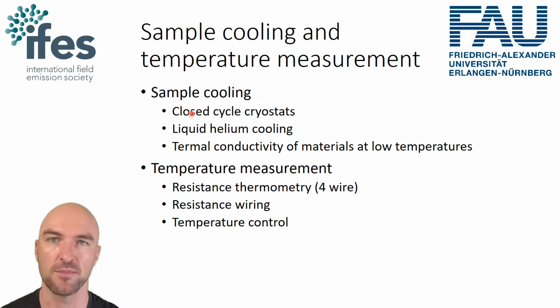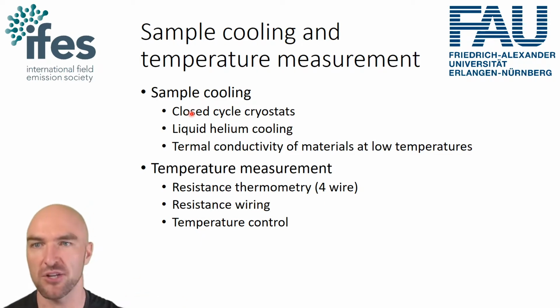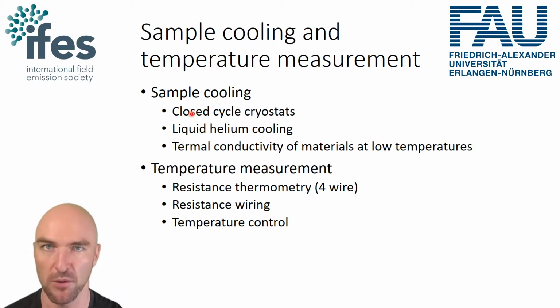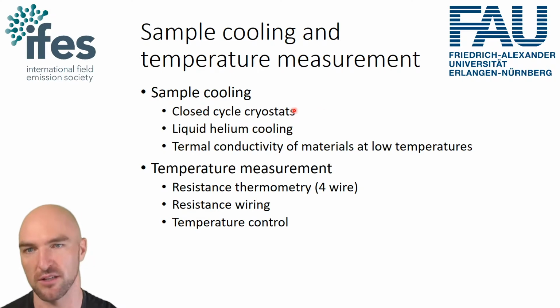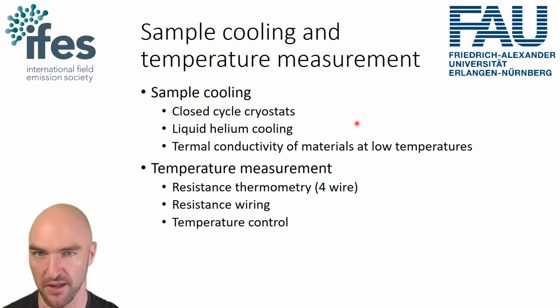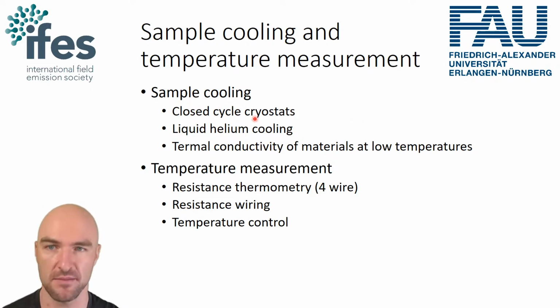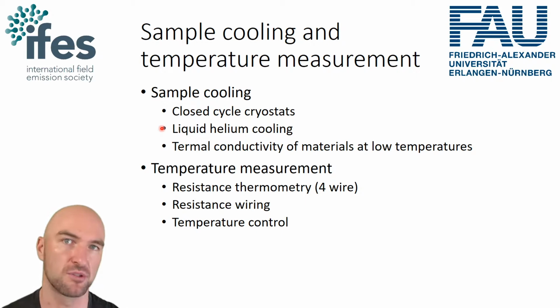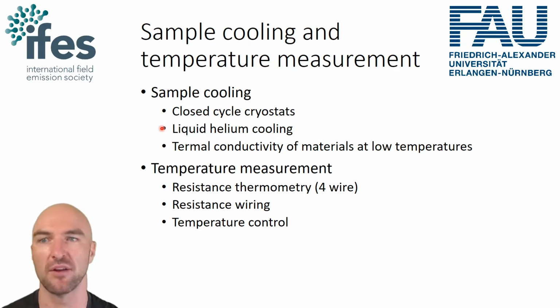You will probably have noticed on various atom probes that you might have, some kind of vibration isolation, and that takes up a lot of design space on the atom probe. The reason for it is that closed cycle cryostats create vibrations, which, especially if you do laser atom probe, matter. If you do voltage atom probe, it usually doesn't matter. If you do laser atom probe, it does matter. And there, liquid helium cooling is the method of choice. But it costs a lot of money to put it in if you don't have it in your lab. But if you have it in your lab, always go with liquid helium cooling.